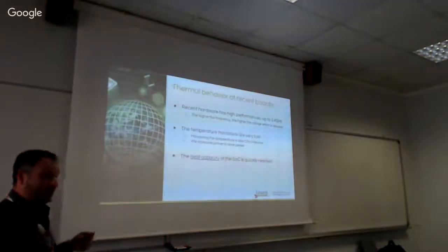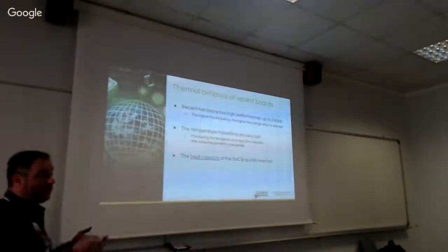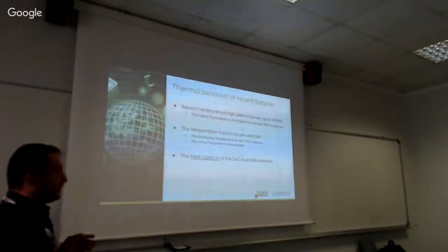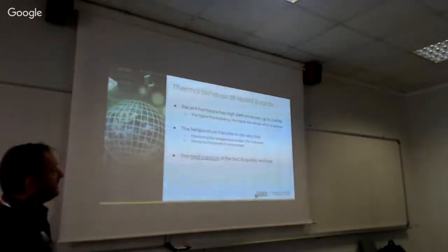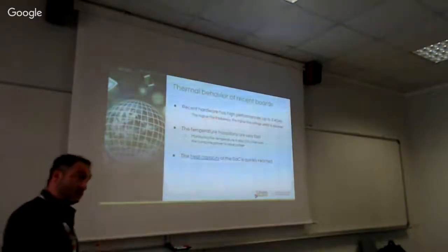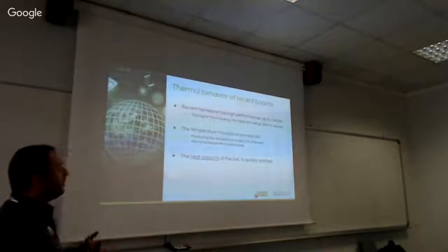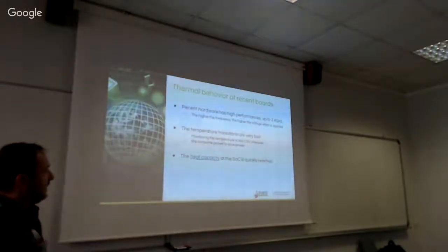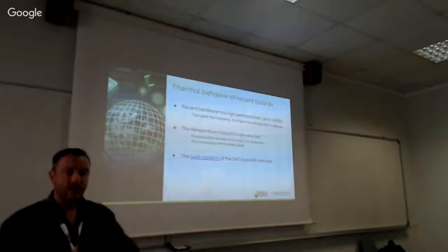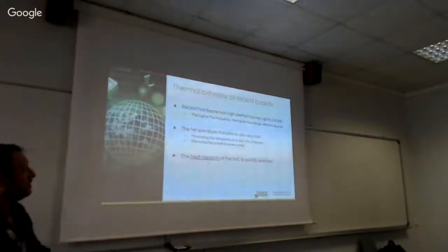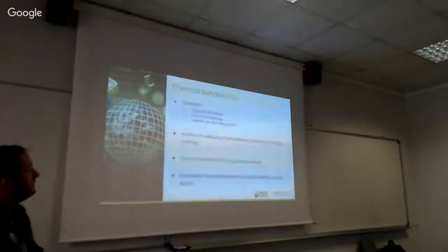So of course, if we want to mitigate this kind of board, we also have to poll very quickly in order to sample the temperature, because the changes are very fast, and that's also CPU intensive. So we are adding more heat. So we consume power to save power. And of course, we are very quickly reaching the heat capacity of the SoC with this kind of hardware.